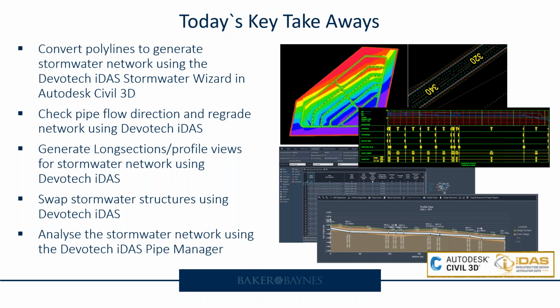But what you would need to do is label your stuff correctly, swap your inlets, draw your catchments in, and then follow through by selecting the flow paths, the catchments, and specifying your coefficients and your times of concentration, the same thing that you would normally do on an Excel sheet. However, this is much more efficient.